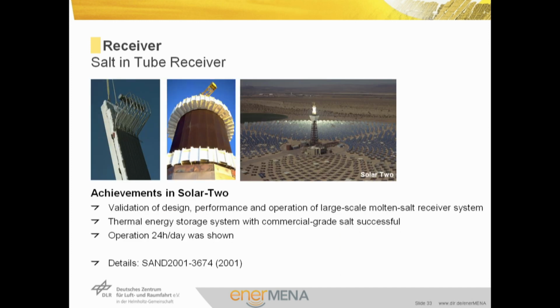The achievements in the Solar 2 projects is the validation of the design, performance and operation of large-scale molten salt receiver systems. It was shown that the thermal energy storage is possible and that the operation 24 hours a day, 7 days a week is possible.